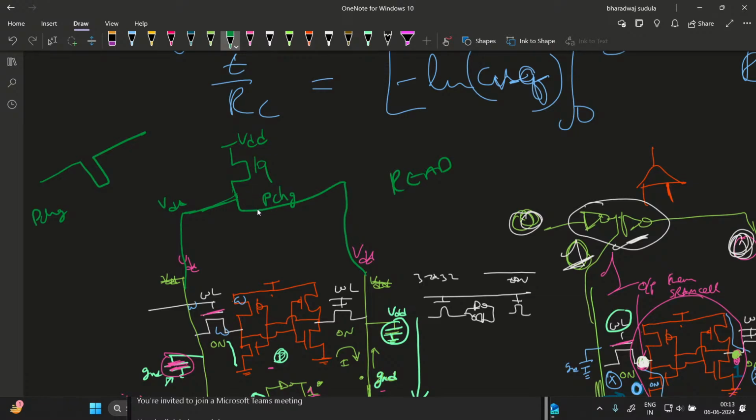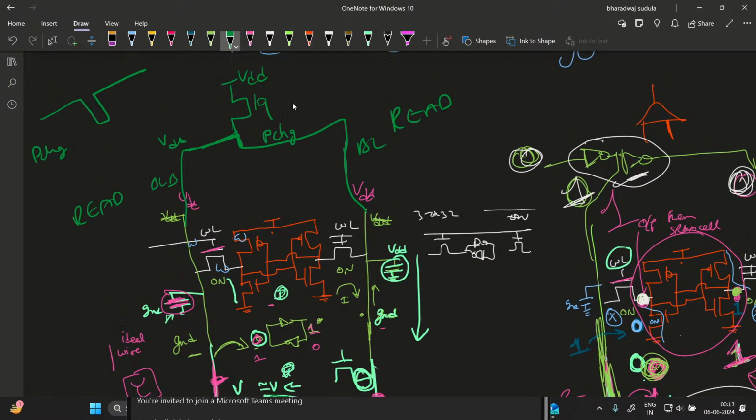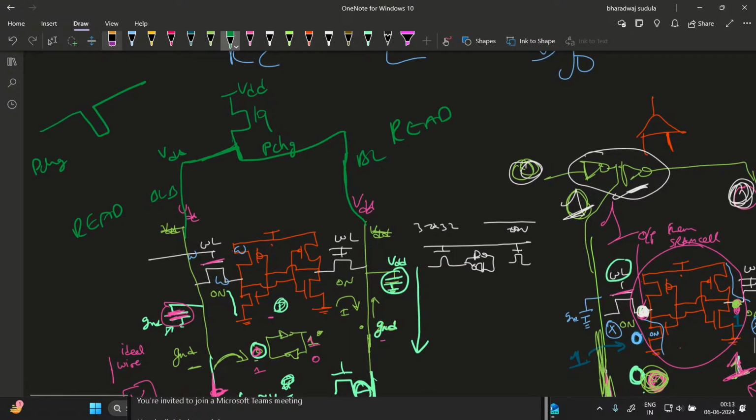But you need to think overall. These bit lines are running all over the SRAM cells onto the SenSAMP, right? This is bit line and this is bit line bar. Here you have simply short circuited them. In read operation it's okay that these two are at VDD, but in write operation, there will be an issue. It should be open circuit, so you separately connect another PMOS to the same pin.